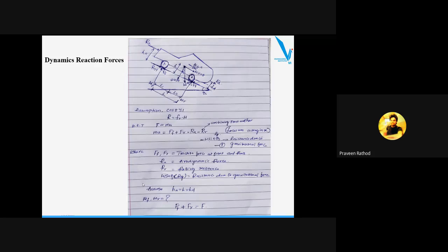You can see tires are made up of elastomer, which has the property of viscoelasticity. Viscous behavior we take as a damper, and elasticity we consider as a spring. So whenever we are modeling any car model, because of these two properties we consider mass, spring as well as damper. This is one reason we are going to do the model of the vehicle.